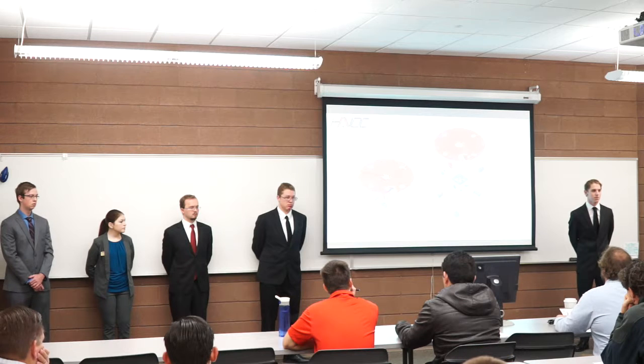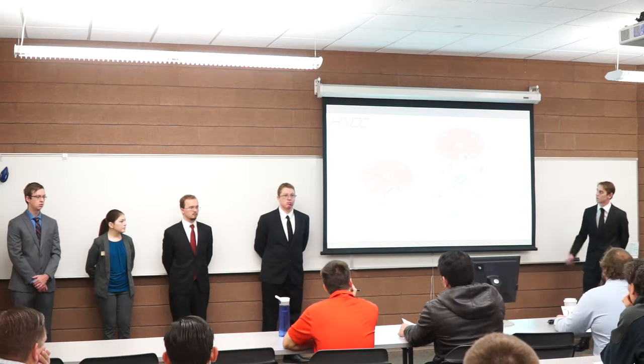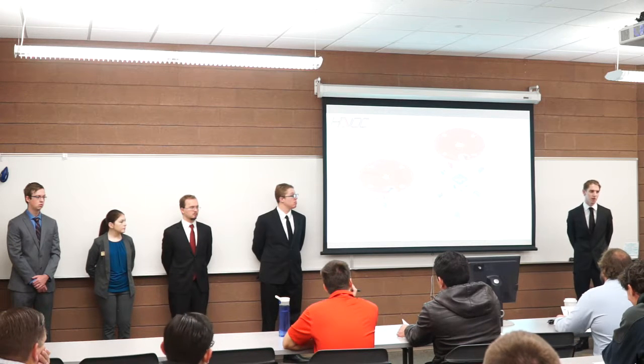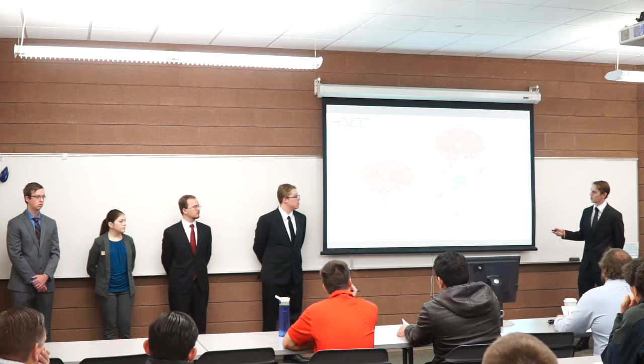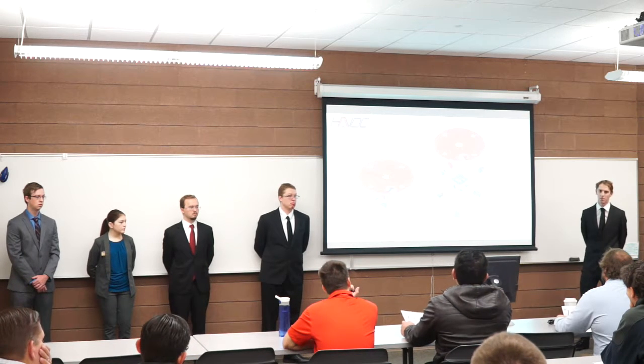Here's the wrist itself, mainly three different parts. We have the top of the wrist, which connects to the palm. It has two holes in it, a tendon passageway through the center, and then there's also a hole right here so that we can fit the nut for the thumb on there.